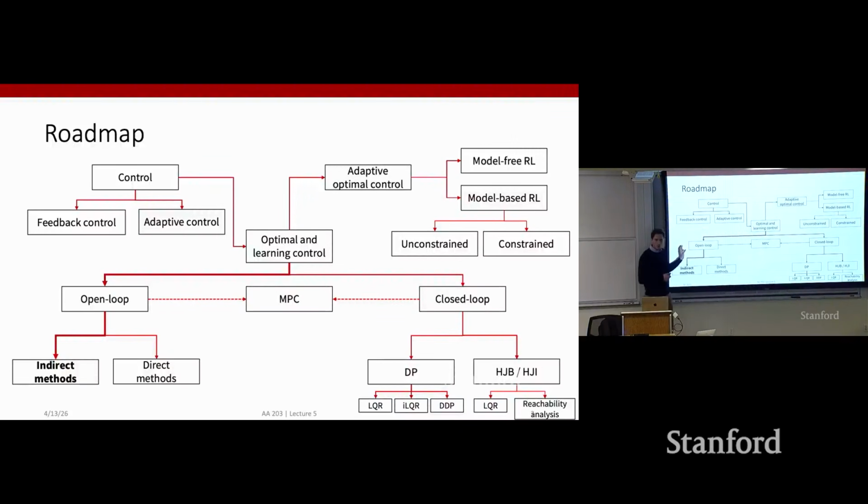And specifically in open loop control, we highlighted the fact that we are interested in an optimal control signal or trajectory, which is only a function of the initial time t. So we are looking for an optimal control trajectory u of t. Within this class of methods, we discussed that there are two macro subcategories: indirect methods and direct methods. Last week, we introduced indirect methods, which, loosely speaking, relate to first of all deriving optimality conditions for the infinite dimensional optimal control problem and solving for those.